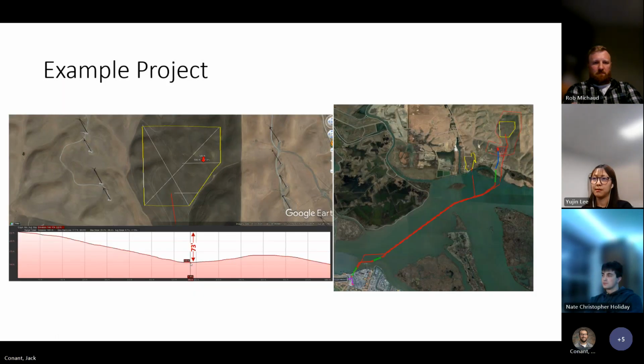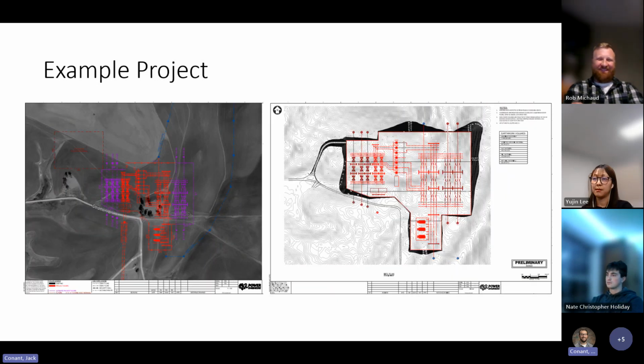I'm gonna be honest with you, I'm not really sure what that one is. Here's another general arrangement though. Just a wonky configuration where they had to do some funny stuff with the buses, but still, if you could see down in there, they did a breaker and a half for the low side. I guess you can't really tell. Maybe this is also a breaker and a half for the high side.